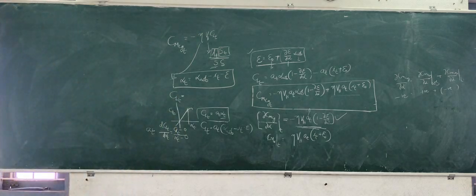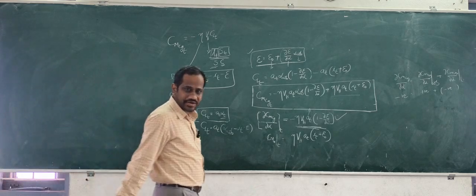Right, tell me. For a positive cambered aerofoil, CM naught is, CMAC is negative. Moment about the aerodynamic center is by the property negative. Since CM naught is equal to CMAC, CM naught is negative. So for the wing alone, if the positive cambered aerofoil is used, the CM naught is finally negative. What is the problem if CM naught is negative?